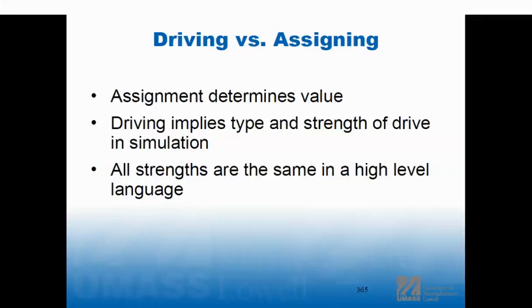And it's more conventional types of Verilog assignments, right? Driving versus assignments, just like we've always done. When you go up to the pad level, you do have to worry about things. Now, here's the easiest example, and it's the most common example, tri-state drivers.